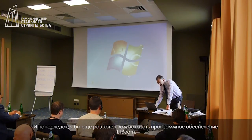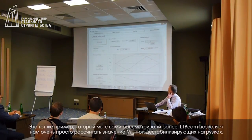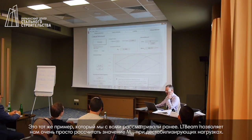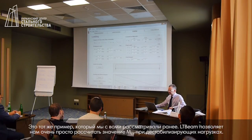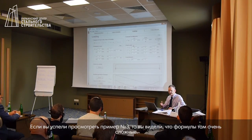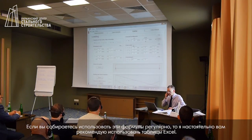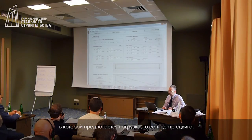I'd finally just like to show you LT beam again. So this is LT beam again. This is the same example that we saw earlier on. LT beam allows us to very easily calculate Mcrit for destabilizing loads. Because if you did look at example 3, you would see that the formula is very, very complicated. If you're going to do the formula more than once, then I would very strongly recommend that you use an Excel spreadsheet. But the free software allows you to introduce destabilizing loads and allows you to introduce the dimension, in this case, above the shear center where the loads are applied.